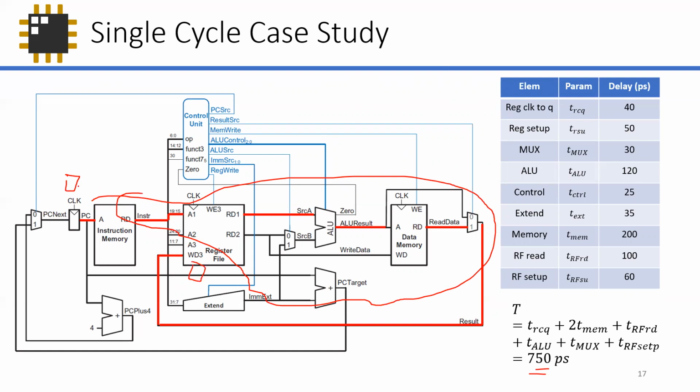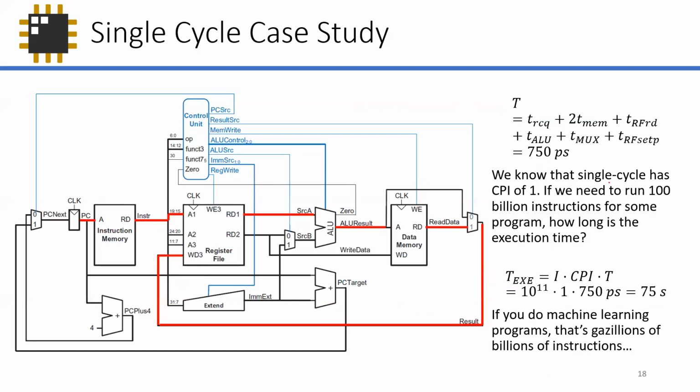So going out here, eventually the output of your combinational block will get back to the register here, and you have to satisfy 750 picoseconds minimum. If you calculate that in frequency, I didn't calculate whatever frequency it is, but if you remember, our CPU time is given by the number of instructions times the period of a single cycle, right?